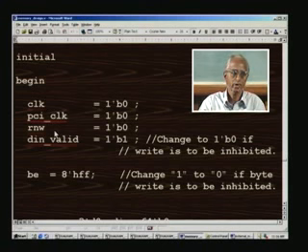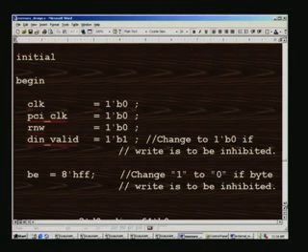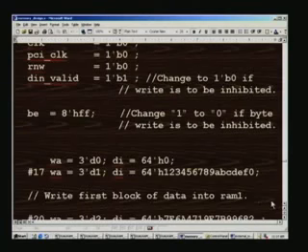So one RAM is in write mode, the other is in read mode. So which RAM, we can make a guess from this. So this is a control to put one RAM in write mode and to put the other RAM in read mode, that is what it means. So this clearly implies it is in read mode, and what will be affected, you have to see. And suppose you want to inhibit the write, all you have to do is make it 0.